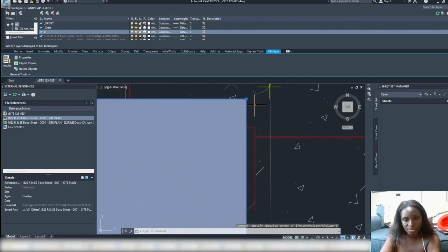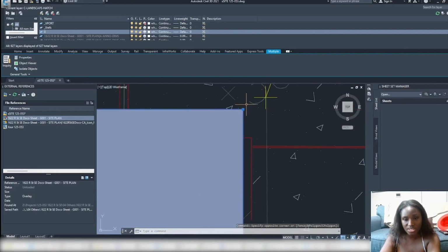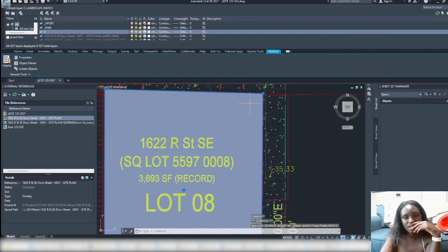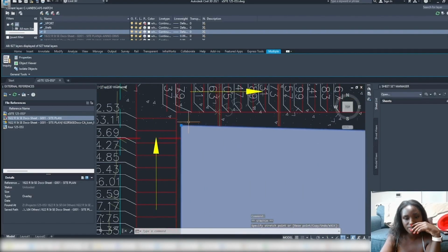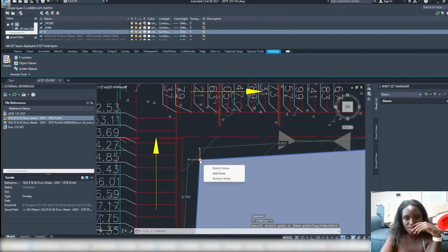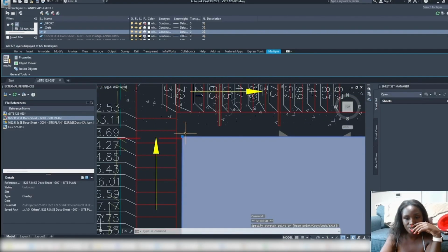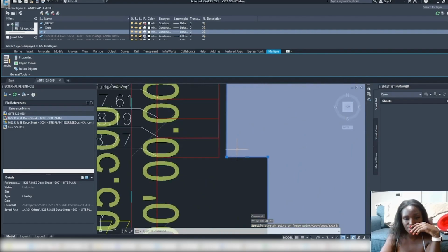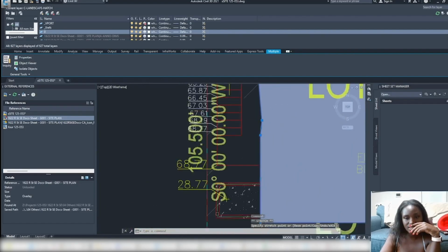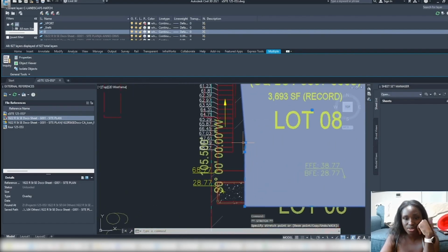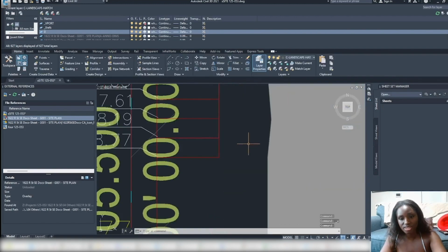You more so follow what a survey does, because the architect doesn't measure from it. They just have different methods of measuring, and there are lines that end up being way straighter compared to what's actually existing. Since the existing foundation isn't changing, that's why we're maintaining what the survey is.